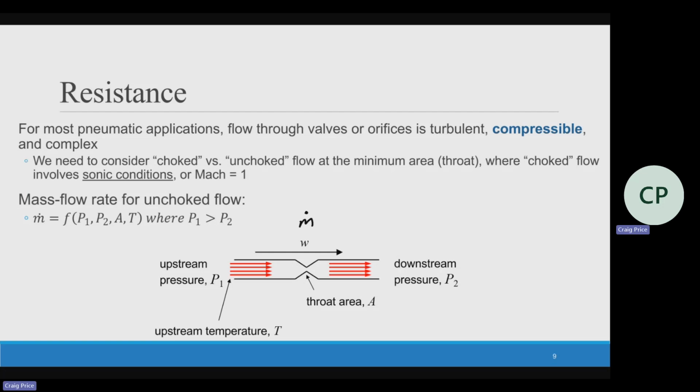I don't know if you remember ever working with this, but to figure out that fluid flow, I need to figure out what is the specific heat of this gas. So for example, for air, the critical pressure ratio is 0.528, but for any other gas, it could be slightly different. And you can look these up, engineering toolbox, whatever. I have my critical pressure ratio.